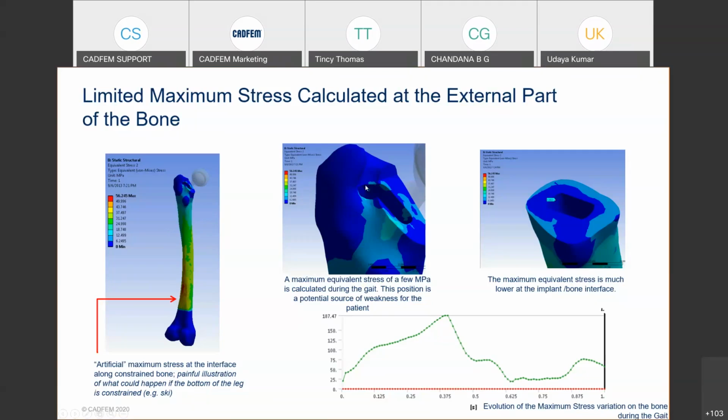Similarly, when we cut off some parts from the bone in order to keep the implant inside securely, we have to test the stresses coming on that contact area also, right? Because if the stresses are higher in this area, the pain for the patient will also be higher. So we have to take that into consideration too, how this implant will be seated into the bone.